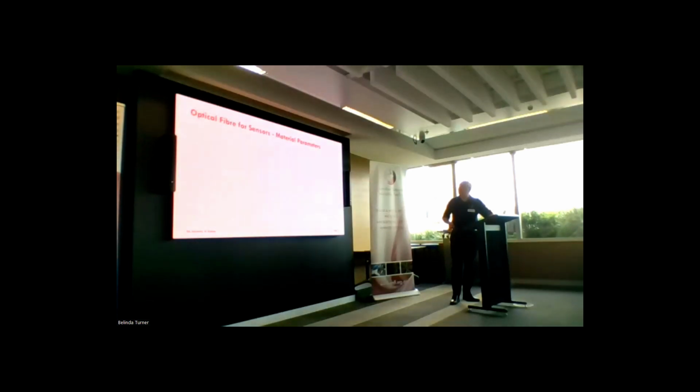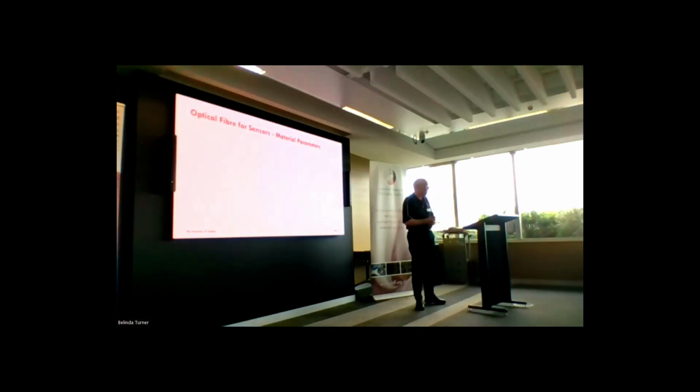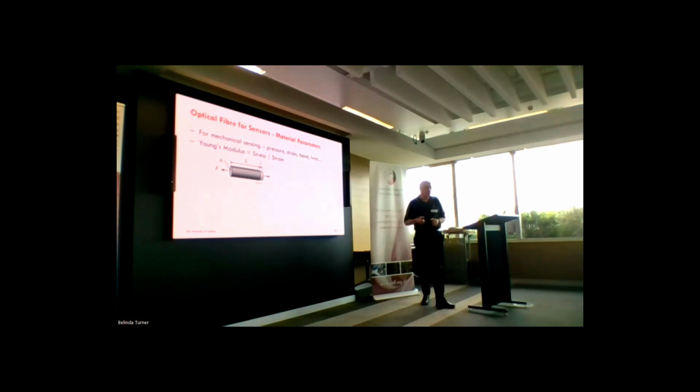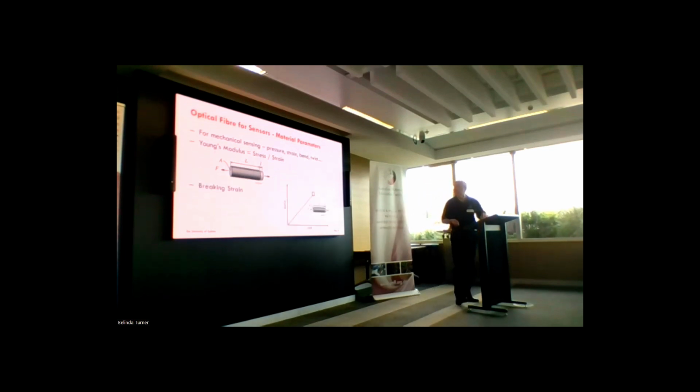Right, so where do I go next? Yes, optical fibers for sensors. Just going to a bit of physics, the important thing if you want to do mechanical sensing is the Young's modulus of the material. This governs the amount of strain, the amount of stretch that you get for a given force or stress that's applied to the material.